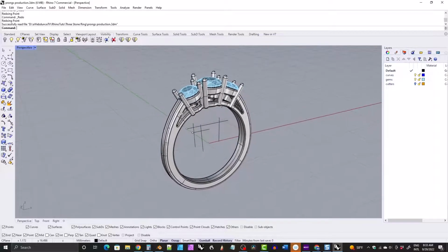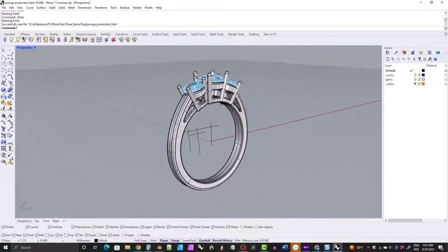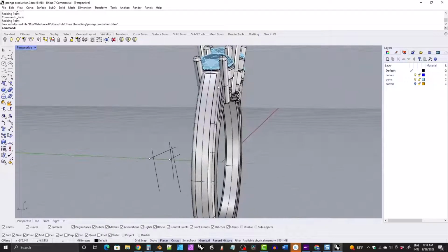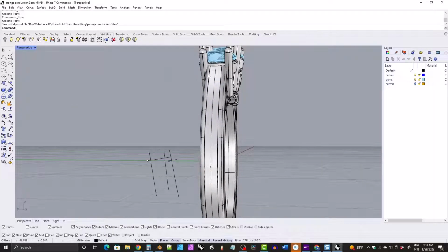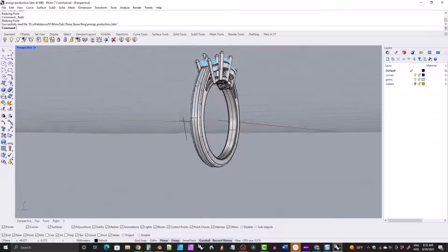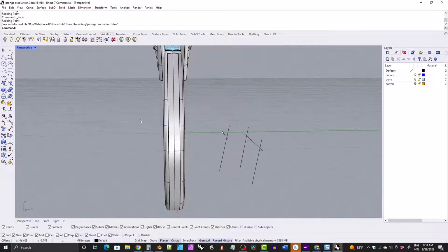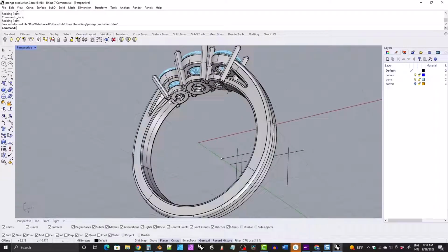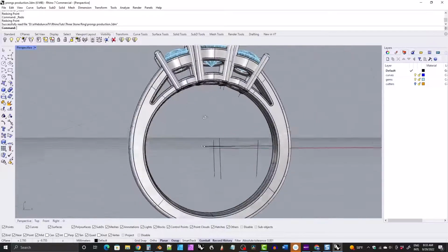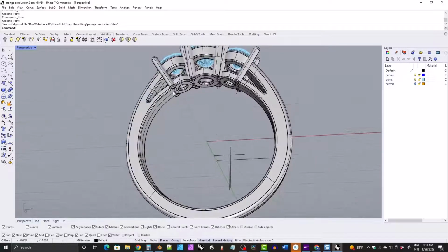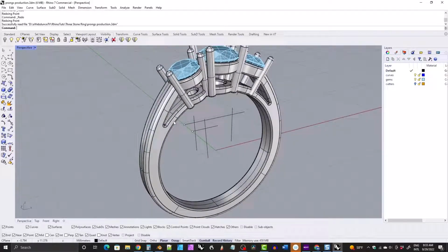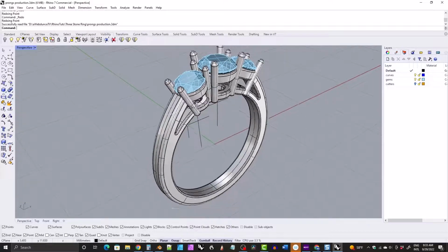We're going to do two different things. One is we're going to make a fancier shank by, instead of having this flat area fillet, we'll have an arc. The other technique we'll cover is how to squeeze in the bottom of the shank to go between these two prongs. So instead of adjusting the prong angle, we could have adjusted this shank. The way we're going to do that is a pretty cool technique that you may use for other things as well, because of the way it works, it makes really nice results.